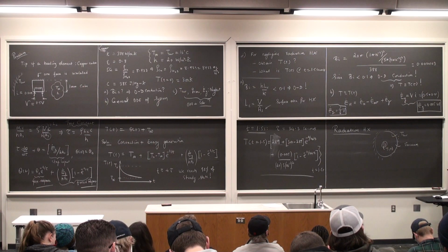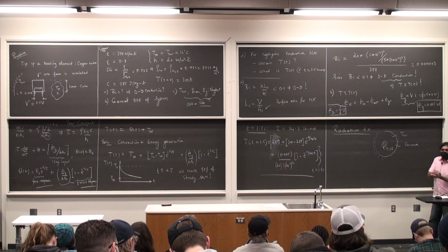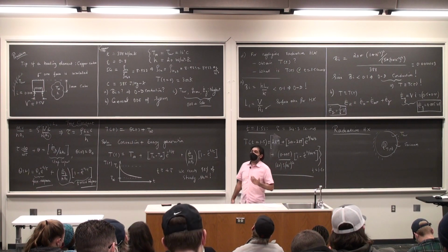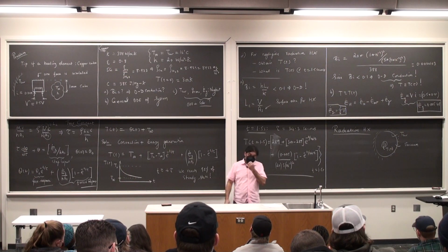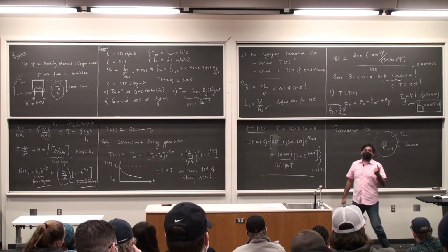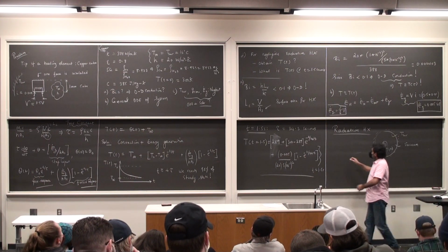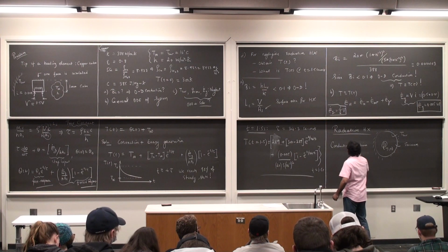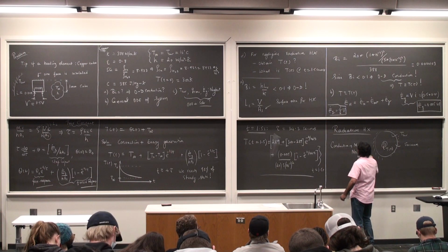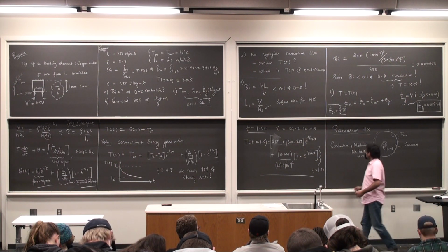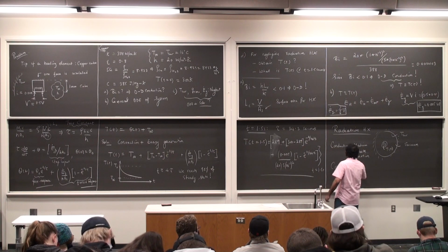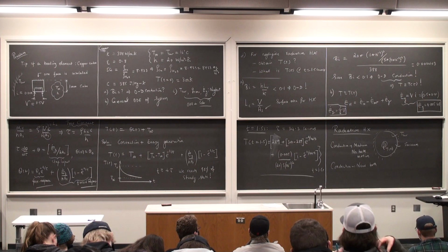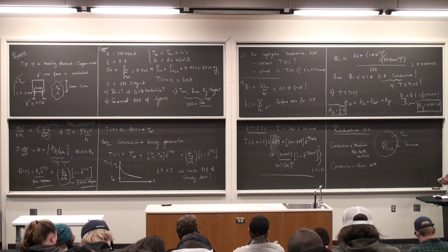So which tells us that there is this third mode of energy transfer in the form of heat, which is taking place independent of the medium that is present between two interacting bodies. And this mode of heat transfer is radiation heat transfer. Okay, so fundamental difference, whether I talk about conduction or convection. In conduction, I need a medium but no bulk motion. In convection, I need both. And for radiative heat transfer, I need neither. Between the interacting bodies, of course, I need an object and a surface. Otherwise, what am I talking about, right?